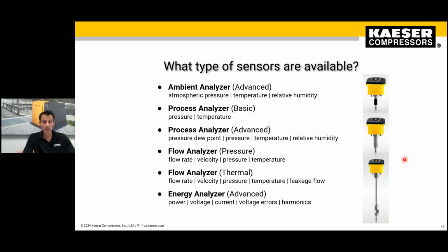Okay, we have spent quite a bit of time talking about different types of sensors and locations of sensors. So thanks, Pascal, for bringing that up. Really, if you can't draw it, then you're not going to understand how the system is operating and really where you would want to measure. I think we covered this with Andrew, but it's a good opportunity to talk about what the big three are, and really that's pressure, flow, and power. And we saw a great example from Pascal of a single track or a double track of compressors with two dryers, and from there you can understand where you might want to install your input data.